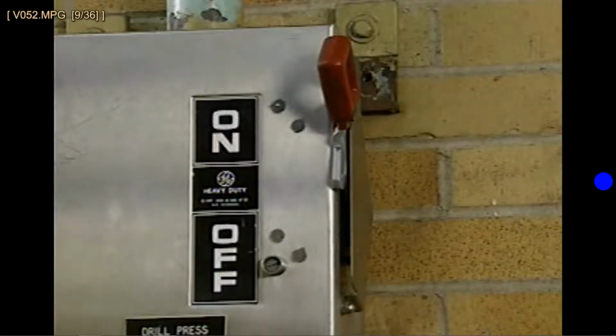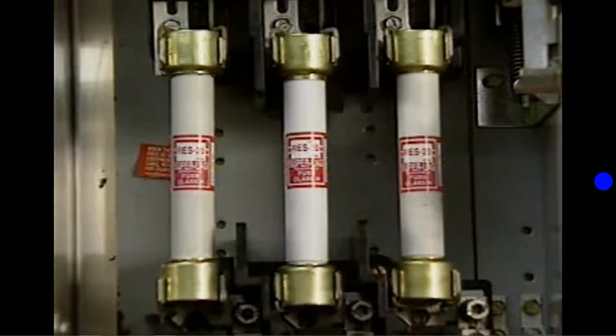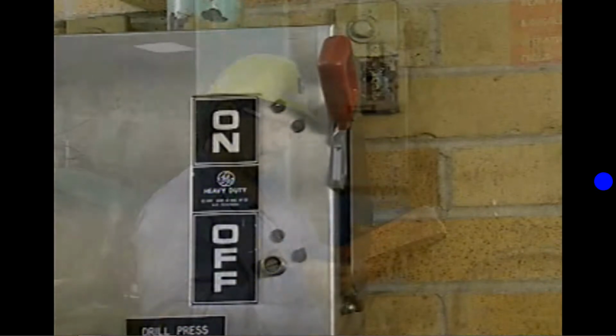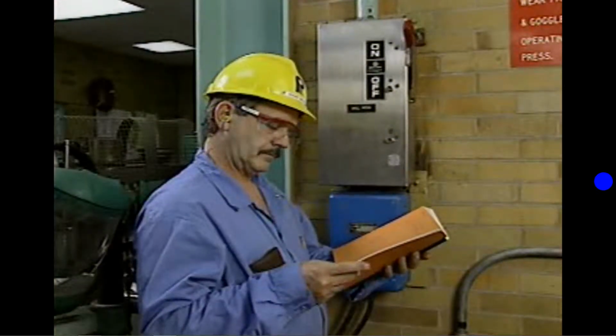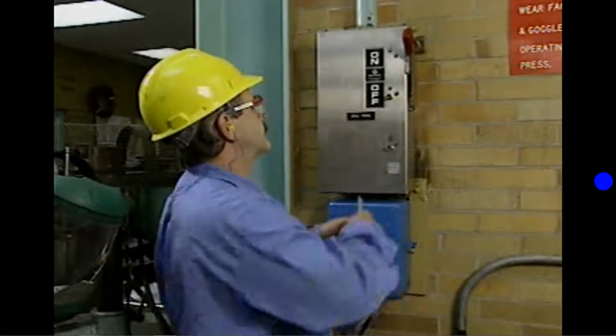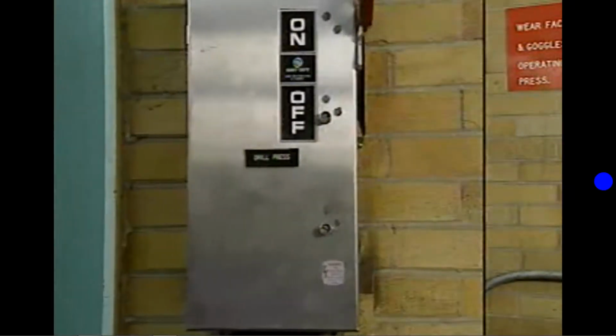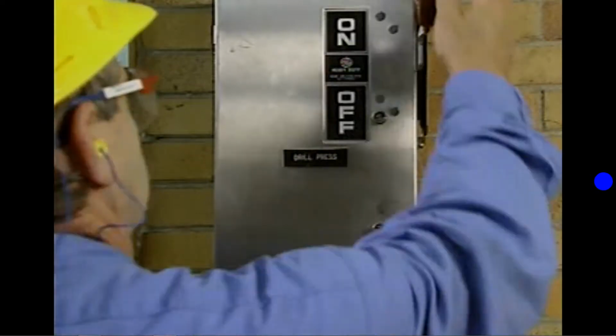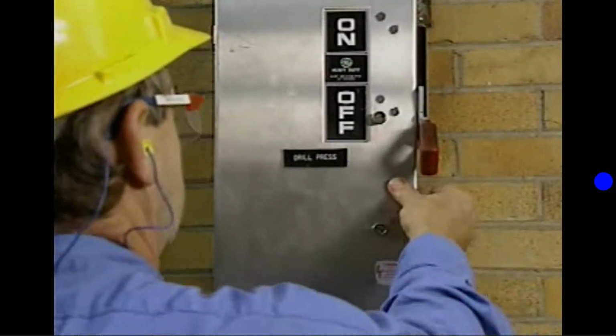In this part, we'll look at safety switches and at fuses that are commonly used in safety switches. Safety switches are often used as disconnect devices in motor branch circuits. A safety switch is usually a knife-type switch that is manually operated by means of a handle and linkage. Many safety switches are interlocked to prevent the doors of their enclosures from being opened unintentionally.